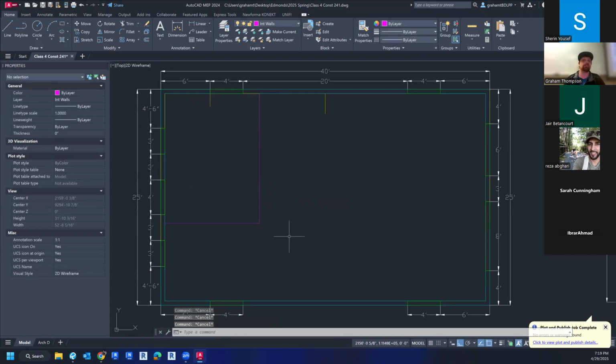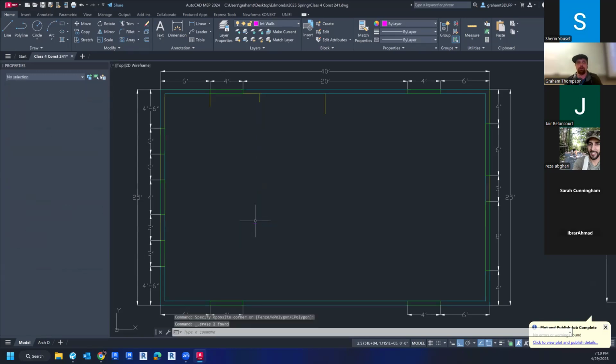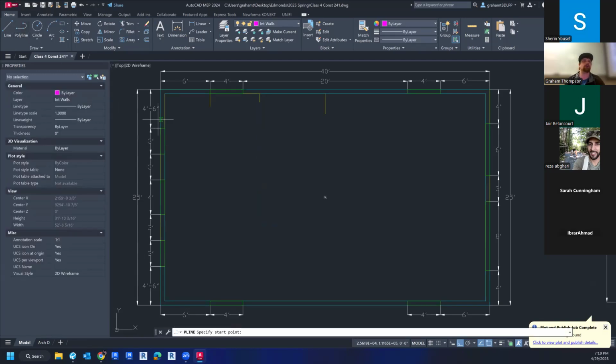I'm going to go ahead and do that, because I think that's worthwhile when you are drawing your walls. If you use a polyline, you can then utilize the offset command and not have to do it multiple times and trim things back together. So I'm going to delete that and draw a polyline, not just a normal line, from the same spot down 15 feet and straight over.